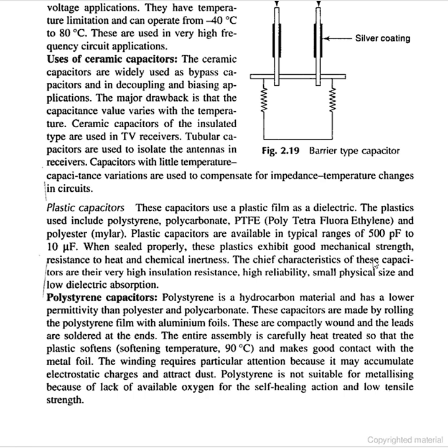The chief characteristics of the capacitors are their very high insulation resistance, high reliability, small physical size, and low dielectric absorption. Polystyrene capacitor. Polystyrene is a hydrocarbon material and has lower permittivity than polyester and polycarbonate. These capacitors are made by rolling the polystyrene film with aluminum foils.